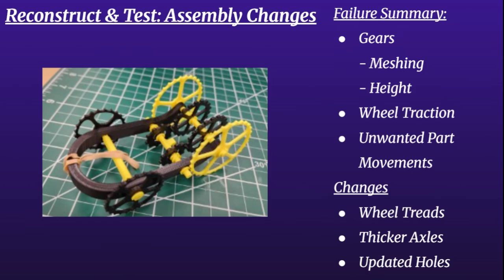The gears couldn't mesh because they couldn't touch, because of the height differences between the axles. I didn't notice this issue because inside Inventor, the gears were floating along the center of the hole, but in person, I failed to account for gravity. So the axle was positioned on the bottom of the hole instead of the middle like in Inventor.